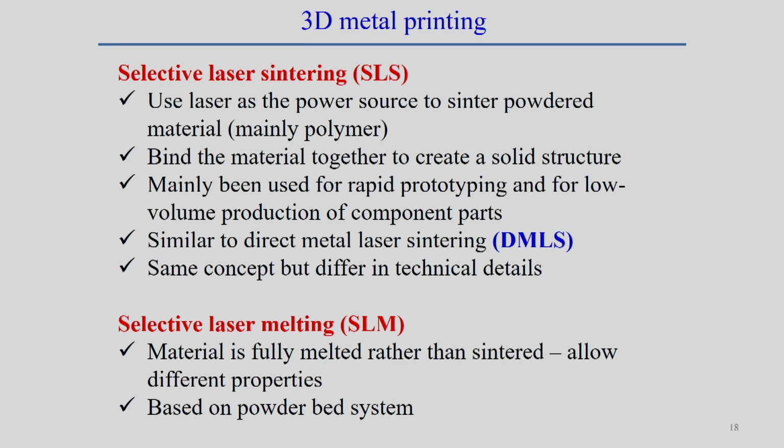They follow the sintering mechanism. This is mainly used in the case of polymers. In the sintering process, we do not cross the melting point temperature, just stay about the melting point of a particular material, and then the binding happens by molecular attraction between these surfaces without melting of the material.